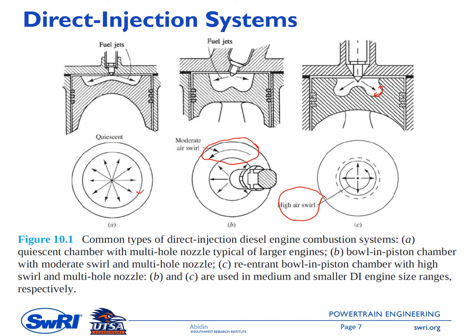If you see the upper side of this piston, the fuel that moves upward will re-enter into the center of the chamber, and that's why this piston profile is usually called re-entrant. It is used to guide the fuel spray to re-enter into the center of the combustion chamber. So there are pros and cons of this re-entrance.